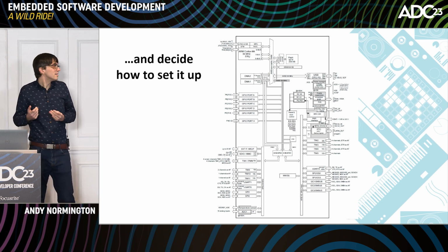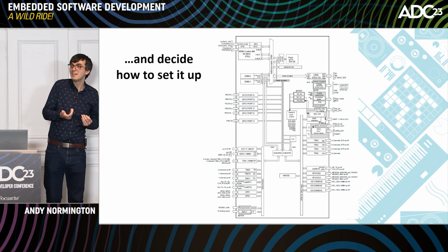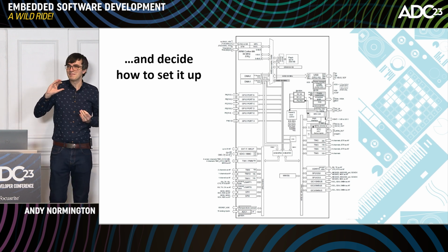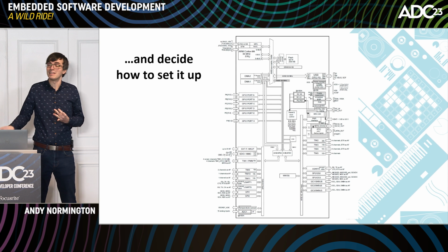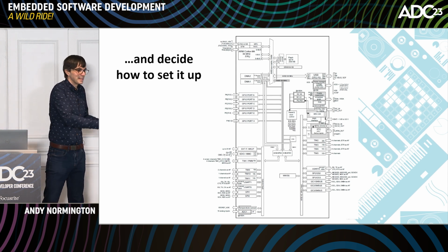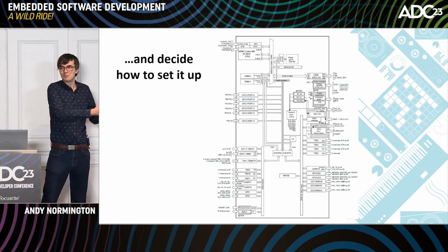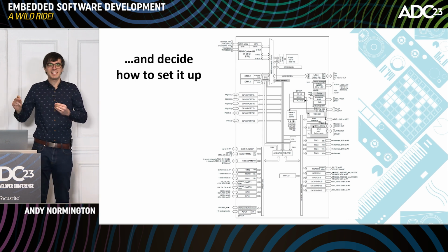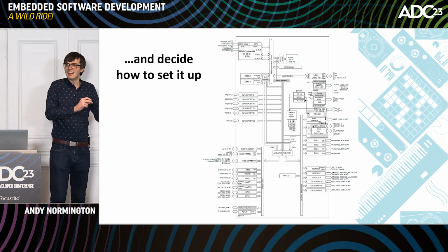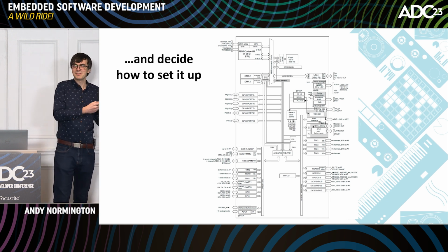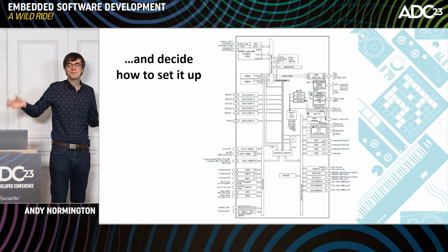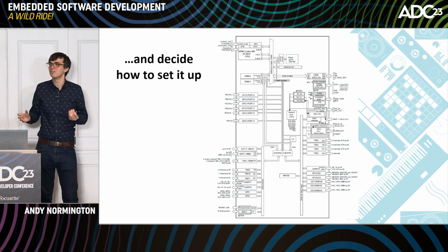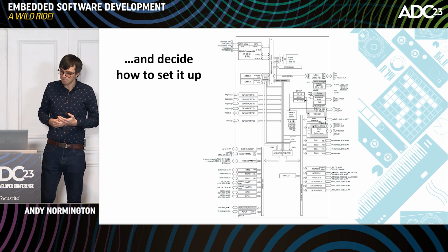Instead of having a timer trigger an interrupt, and then we service that and trigger an ADC sample, and then we get an interrupt when it's done, and we copy that sample out of the peripheral into memory. If we're smart at this point, we can spot that timer 3 can trigger ADC1 directly, and then the DMA peripheral can talk to ADC1 directly and copy that out of the peripheral into memory for us, and the core didn't even have to wake up.